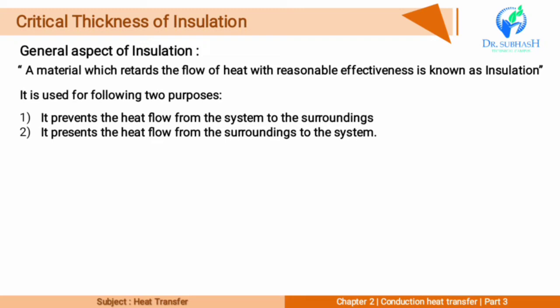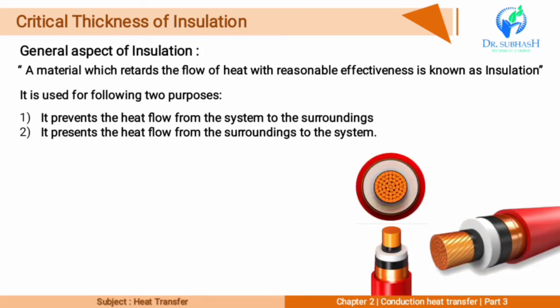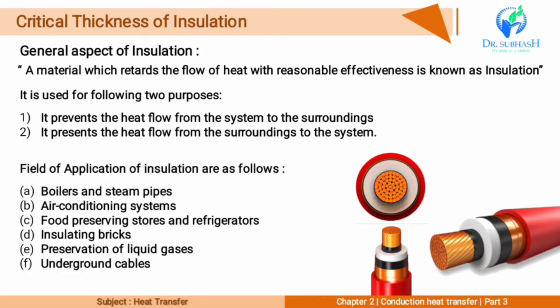system. Contrary to the common belief that addition of insulating material on a surface always brings about a decrease in the heat transfer rate, there are so many examples when the addition of insulation to the outside surfaces of cylinders or spheres does not reduce the heat loss.